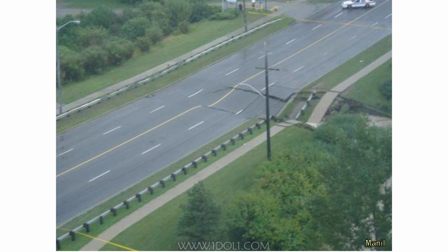And if the pipe is too small, what happens is that the water level rises really high upstream. And when the water level is rising like that, then it can not only flow through the culvert itself, but it seeps through the soil on the outside of the culvert, like around the bedding that was under the culvert and the fill that went on top of the culvert.